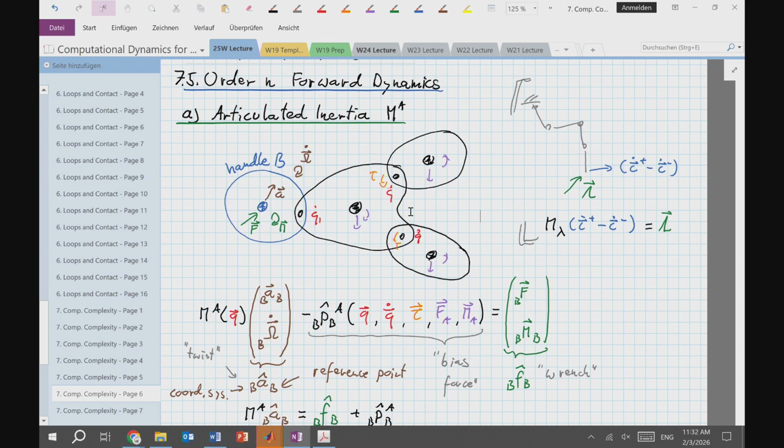We kind of know that because if stuff is moving in this articulated thing, we get bias accelerations, we get inertial forces, which we will feel here, right? So that should make sense. If there's a motor, if that creates some torque, we should feel a reaction here. If there are external forces, we should feel a reaction here. But the important notion is that none of this is acceleration dependent. Yeah? The accelerations come in only linearly.